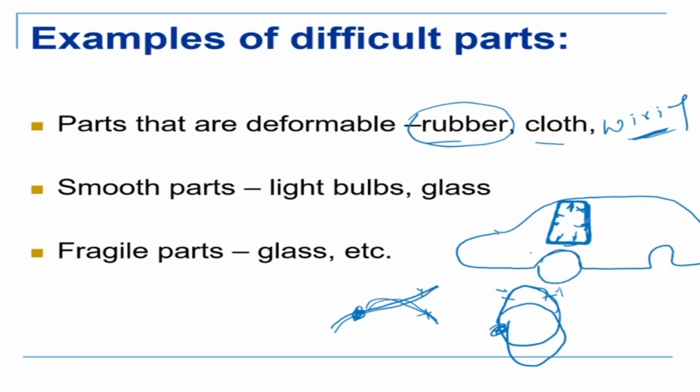Mounting of the wheel. The wheel is mounted like that. The wheel is carried by an overhead crane, and then the human being guides the wheel, fixes it onto the body on those four bolts which are there. Then he'll put the nut and tighten it. That's another one, something a robot cannot do. Very interesting thing: a robot cannot tighten a nut and a bolt very easily. Why? Because when you tighten a nut, you cannot define the points in space. Why can you not define the points in space? Because of whether the threads have set.